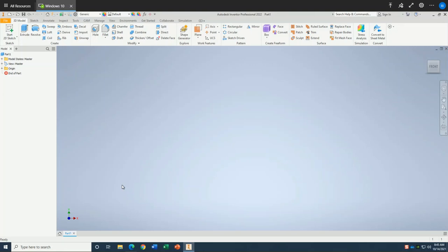You need to select, as usual, a plane and then make a sketch from that plane. To select the plane, on the left you have the browser, and there's an origin folder, and there's a plus button. When you click on the plus button, you will see what is inside the origin. Then we have 3 planes to choose from. I'm going to go with the YZ plane. The YZ plane is a side view of the building, and that's exactly what I want to do.